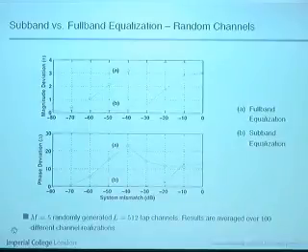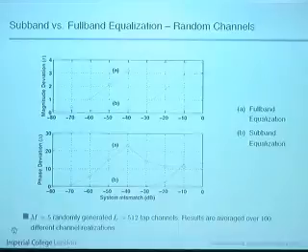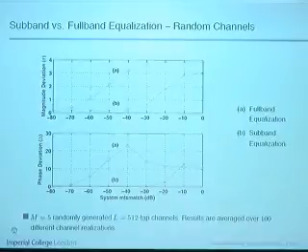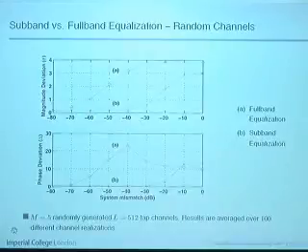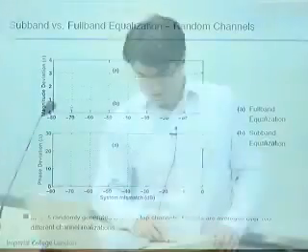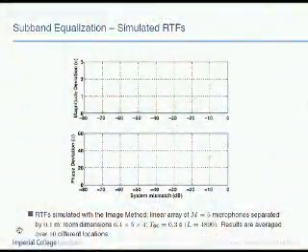So for the full band multi-channel LS equalization, you get what we got before, pretty bad distortion as you start getting inaccuracies in your estimates. Whilst with the subband case, you get a much more graceful degradation, now that the filters are much shorter. And here is a case with longer impulse responses.